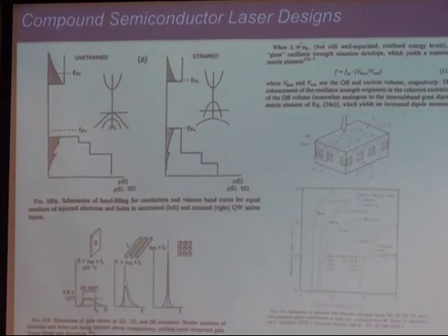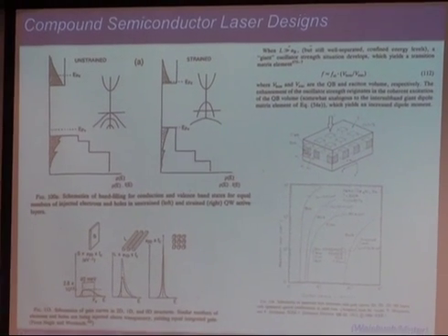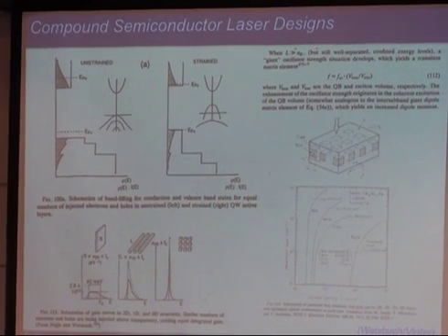One of the issues with quantum dot lasers is it's very hard typically when you grow to have all the quantum dots the same size. We will talk about growth, structure and growth and all that, starting Thursday. So today is the last class on electronic or photonic properties. But we'll see that the dots that are used for lasers are typically self-assembled. You don't predefine the sizes. So there's always a broadening in the size distribution, and that's one of the challenges in making very good quantum dot lasers. So this is not as sharp. There's some broadening because of size distribution.